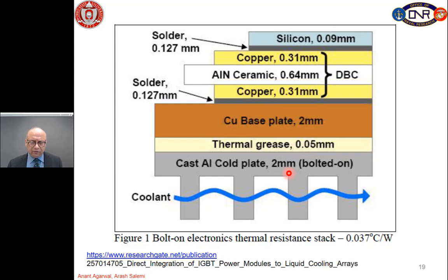So, the function of this power module is to connect a lot of devices in parallel to give us higher current rating, but at the same time provide means of removing the heat from the silicon device or the silicon carbide device.